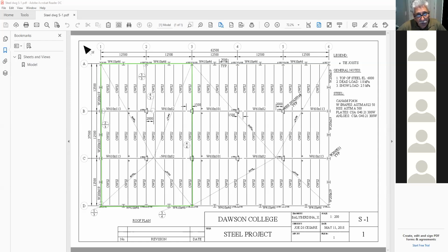So for example, here I have 25 to 12,500 in this direction. So in theory, this slope here is 4% in this direction. You understand? So how do we know where to place that drain? Where you have to create at least 2%. Oh, okay, so it depends on the slope. Exactly. In other words, you would work it out.